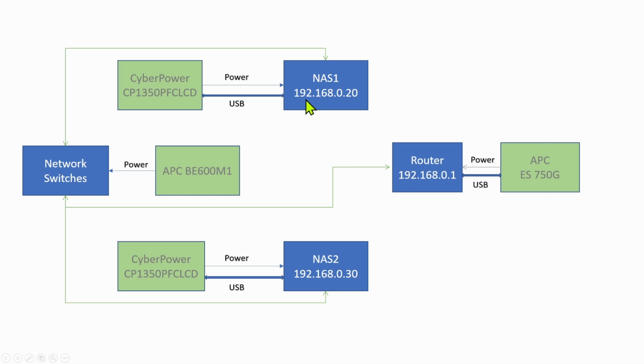Imagine I've got some interface here, and that interface is connected to the network switch. And also let us assume for a moment this hardware or interface is also connected to the UPS via USB. Now you can tell by this assumption this piece of hardware, which is connected to the network, can basically key off the information from each one of these UPS, right? And can collate the information and report it to you. So this is what the NUT server does.